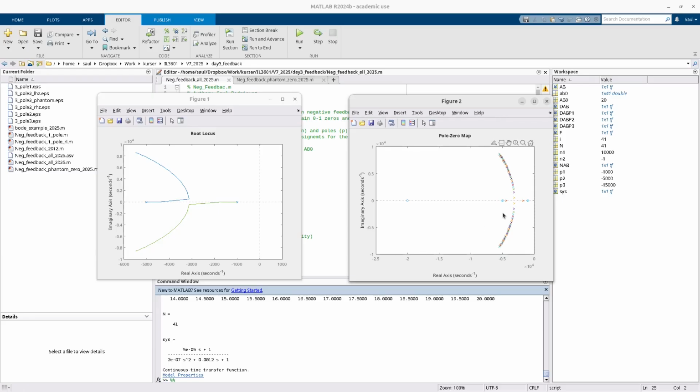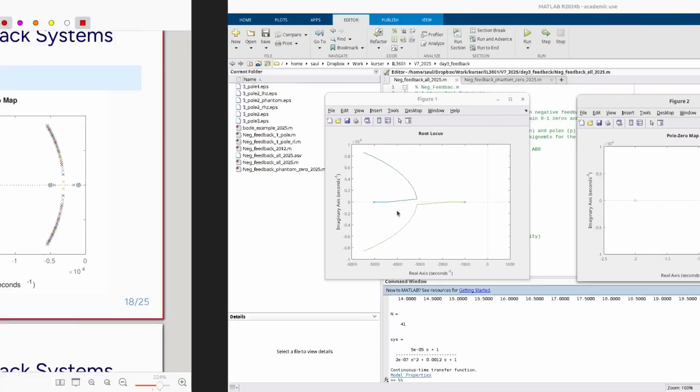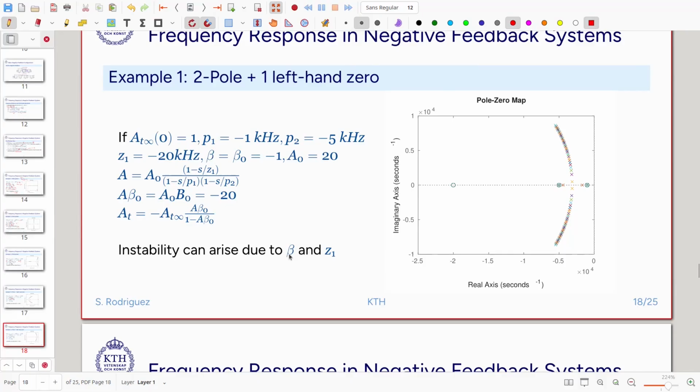Okay, so we can see the resting positions of the poles at the end. So this is my root locus. So zeros attract poles that split. Still, there might be issues with instability. As I mentioned before, if I had put the zero somewhere here, the trajectories would have been like this instead and could deteriorate the stability. In this particular case, I put the zero here and then they went in these directions.